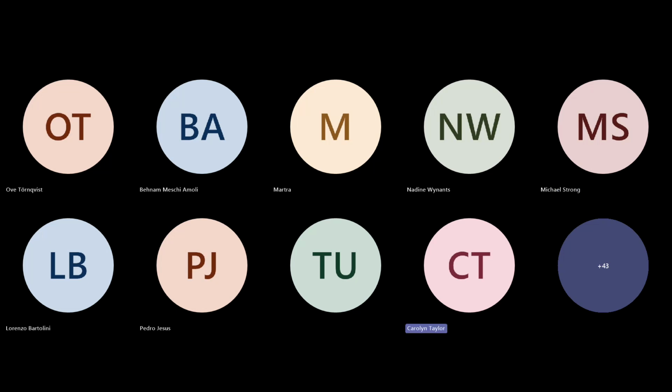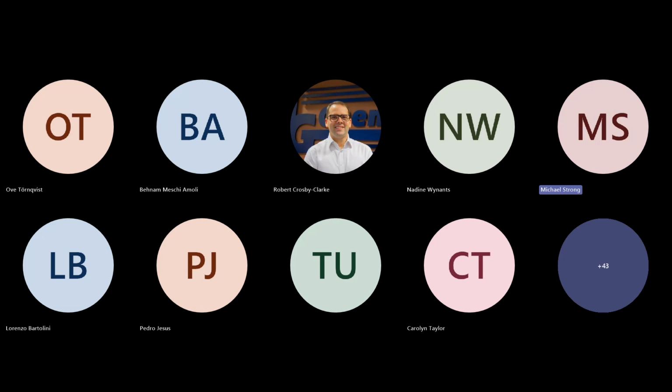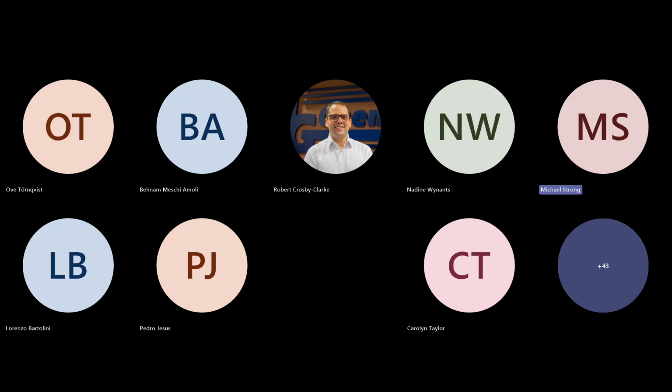Okay, and how does that stand for insulation coatings? Insulation coatings, again, you typically need about 1 to 2 mils, but there is no external standard for dry film thickness. So it's very consistent with conformal coatings, 1 to 2 mils, good overall coverage, and you're probably protected up to 5,000, 10,000 volts. So that is sufficient. Okay, perfect. Thank you.